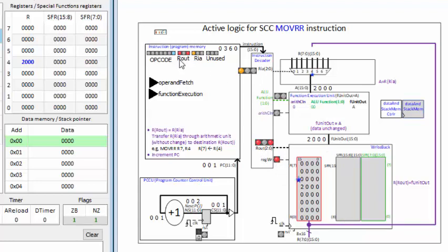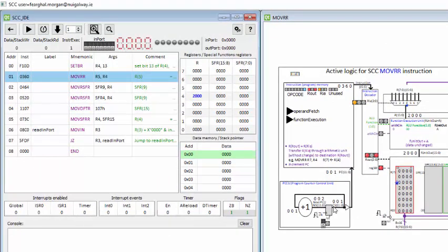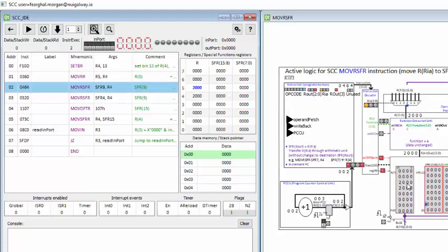In the instruction, the destination register output, 3-bit register for R0 to R7, is 101, which is 5, and the star illustrates that the register that will be written to when the instruction executes is register 5, and it will take the value 2000. The program counter will increment from 1 to 2. So if I step the instruction, 2000 is now in register 5, here also.